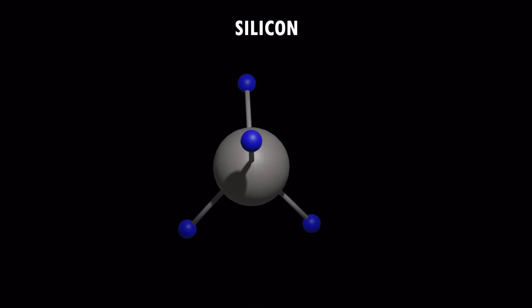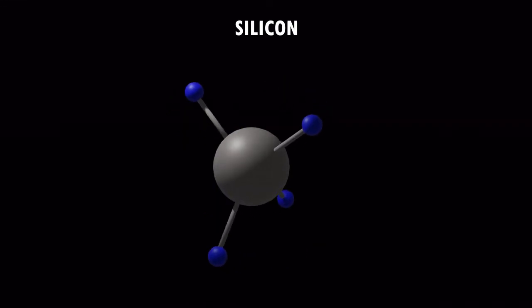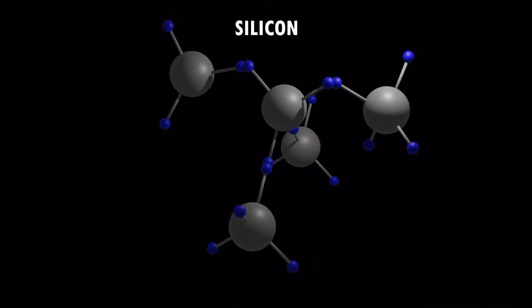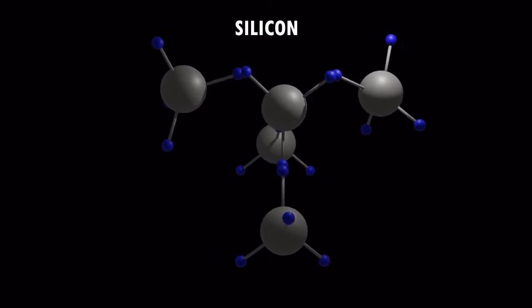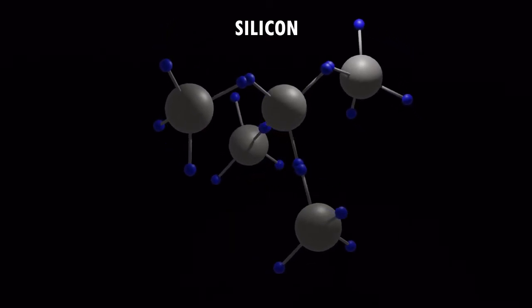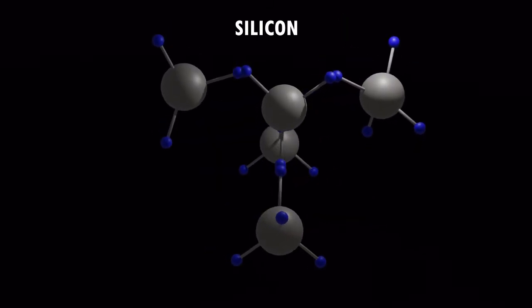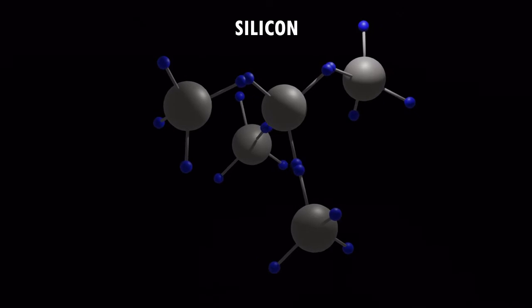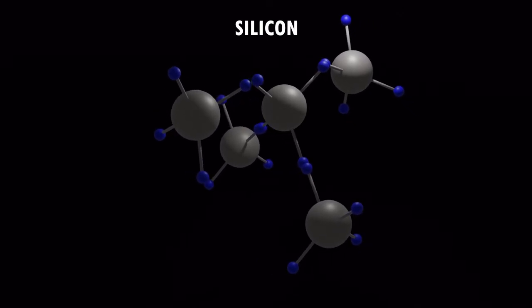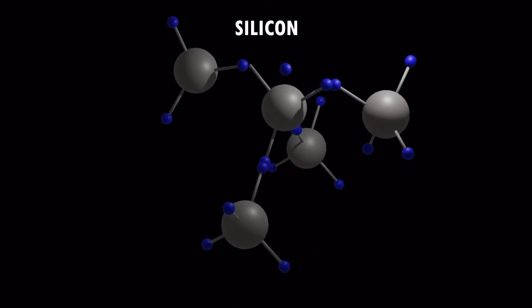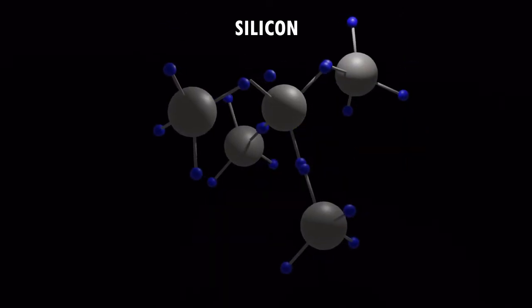Let us consider a silicon atom which has 4 valence electrons in its outermost orbit. These valence electrons bind with the neighbouring silicon atoms through covalent bonding to form the crystalline structure of the silicon. At the present state, there are no free electrons in silicon to conduct electricity, so it behaves like an insulator. But when an external energy in the form of voltage is applied to the material, some electrons break from the covalent bond and become free electrons.